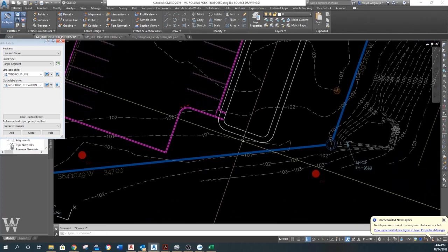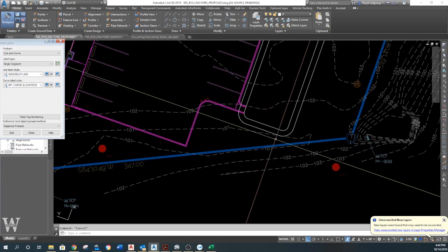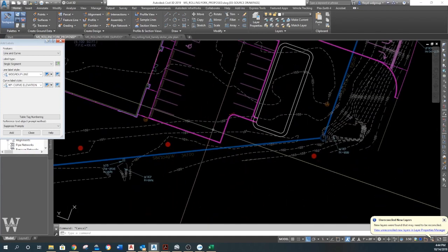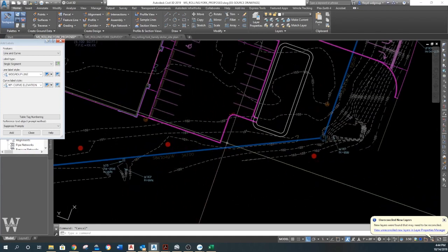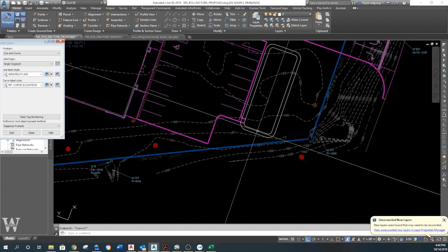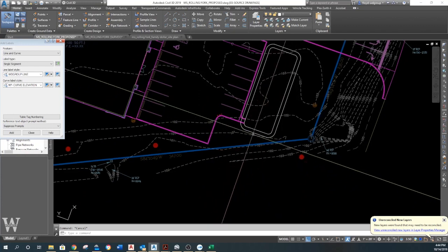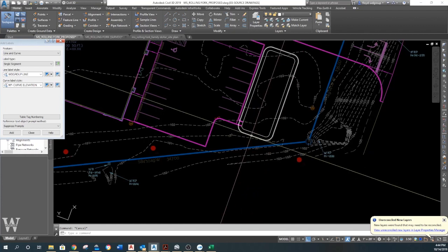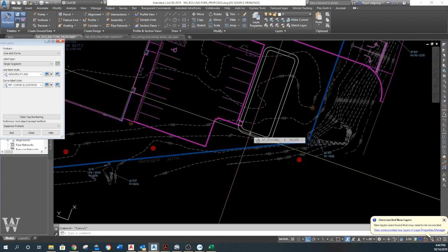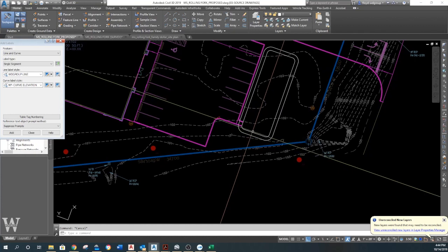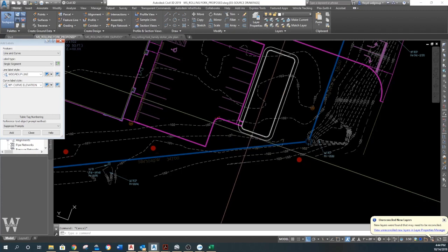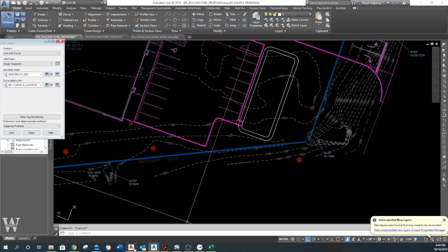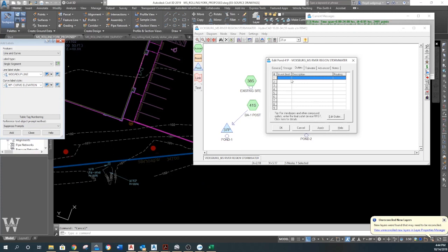Now this outlet, what we're going to do here, because this is 101 right here. This is actually that ditch, kind of going back, trying to drain back that way. So we'll regrade this just a little bit right here, and we'll put in a concrete flume out here. We'll show a detail that says it can be concrete or grass, and they'll just put a little flume in here. I bet we can make this work with the flume. That's the cheapest thing we can do.